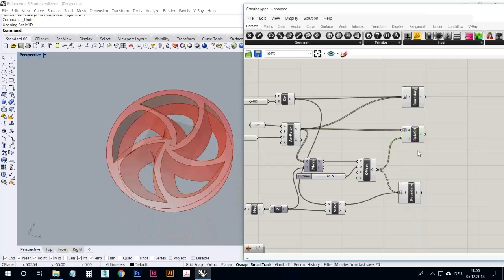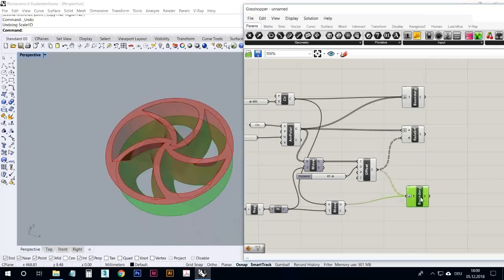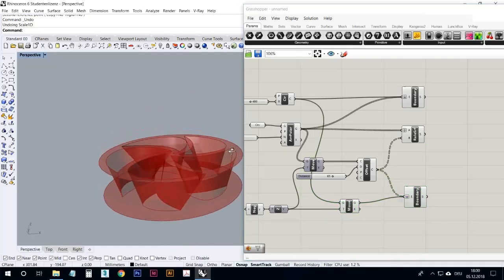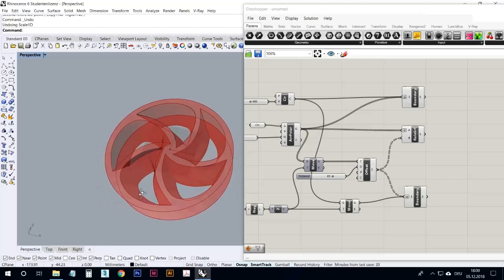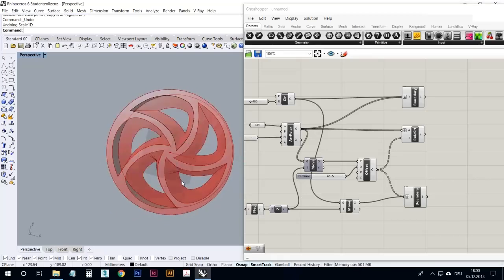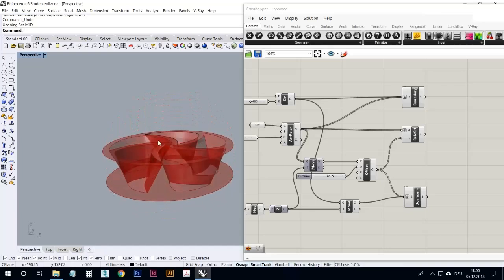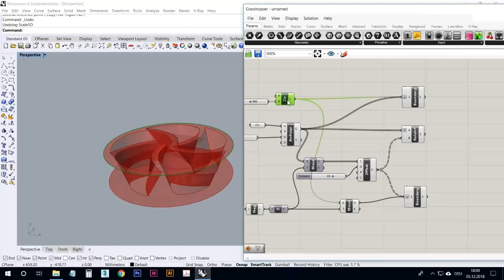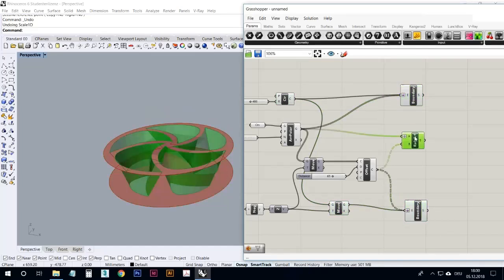So let's now combine all these surfaces to make a closed polysurface. And something that is easily forgotten now: we don't have a wall on the outside, so we need 2 sets of walls. First set contains these 5 walls, and one other set contains only 1 wall, the outside one here. And that is actually the circles, right? So if we keep the structure like this: top floor, bottom floor, walls, and another set of walls.